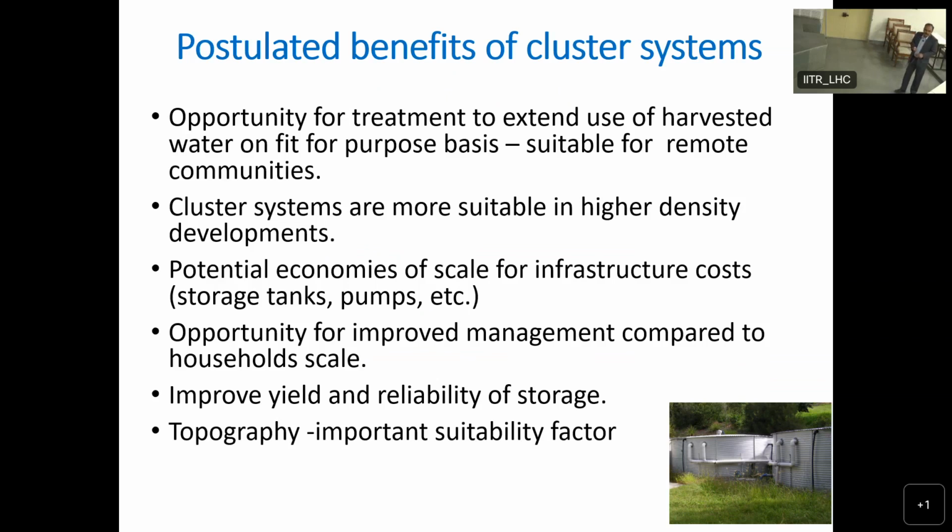Topography is a very important factor. Where there is a flat topography, the number of houses you can have in a cluster scale of communal system can be smaller. But if you have a topography or slope, then depending upon how you design your system, and that is something we'll be talking about, you need to have your collection system at the right center so the cost of collection can be minimized.